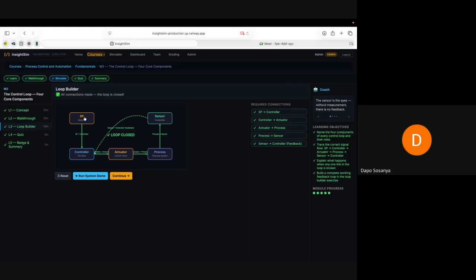When you know how signal flows, of course, you know that the SP, you are not actually wiring it. You are writing. You sit on your computer, you just type a value, and then it goes into the SP, right? But from your controller, you wire your controller, the cards, your analog output to your actuator, and then your actuator to the process to the sensor, and then the sensor delivers data back to the controller, and you have your process.